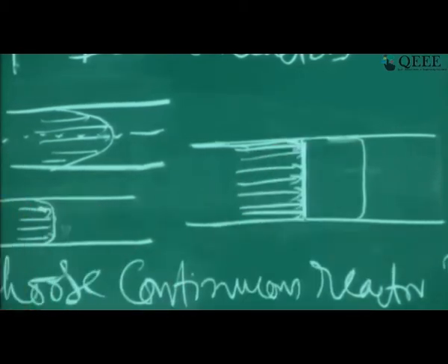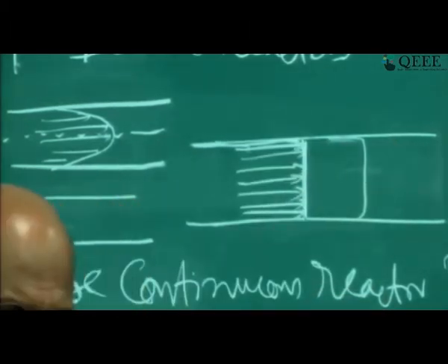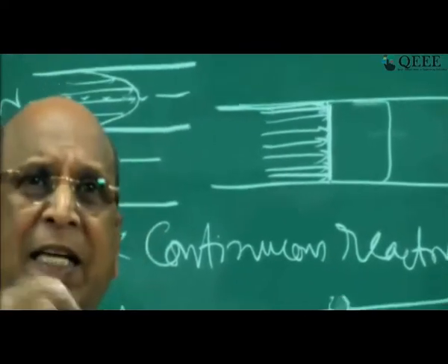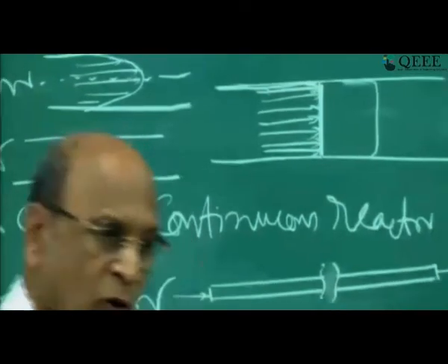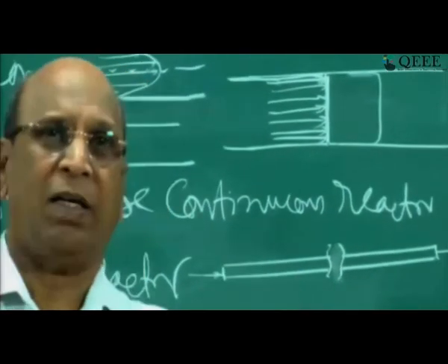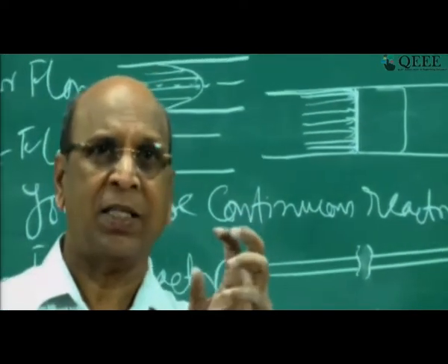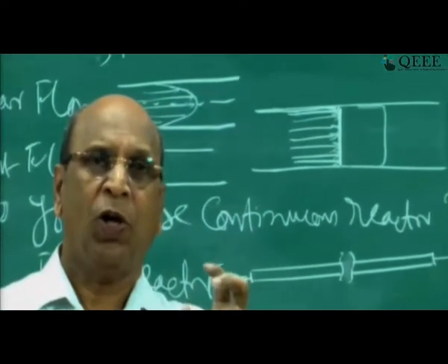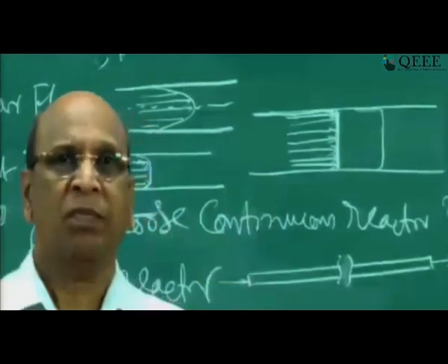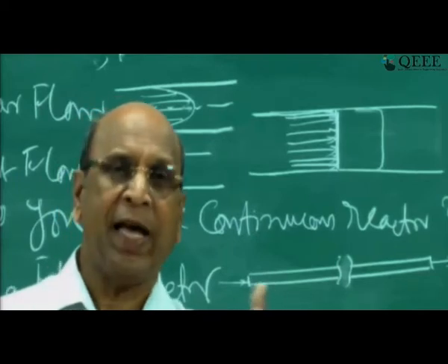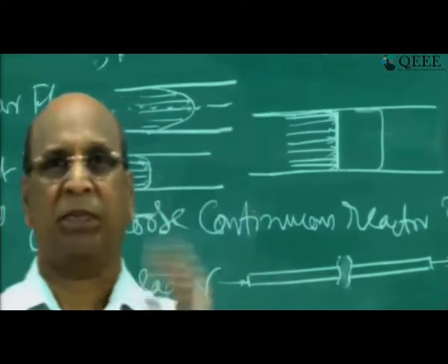The ideal definition of plug flow is this, or in other words, the straightforward, I think the correct, necessary and sufficient condition is that by defining this, we have each and every particle, every molecule. Molecule is very difficult to visualize, so that's why we say particles. Each and every particle in plug flow will spend exactly the same residence time. Again defining in slightly different way, each and every particle spends exactly the same residence time inside the reactor.